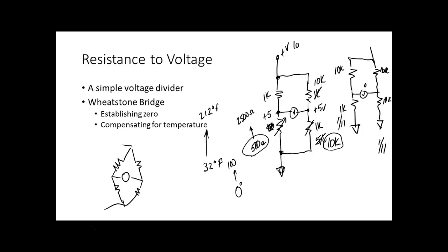And what we would do is we didn't adjust it at the Wheatstone Bridge. We adjusted it at the indicator. What we would do is we'd put 0 weight on it, and then we'd go in and 0 our scale. And then we'd come up and we'd put a certain amount of weight on it, and we'd tell the digital analog converter that was the weight, right? Understand? And then we'd set what they call the span of the scale. But we use a Wheatstone, load cells use Wheatstone bridges because of another feature we'll look at.